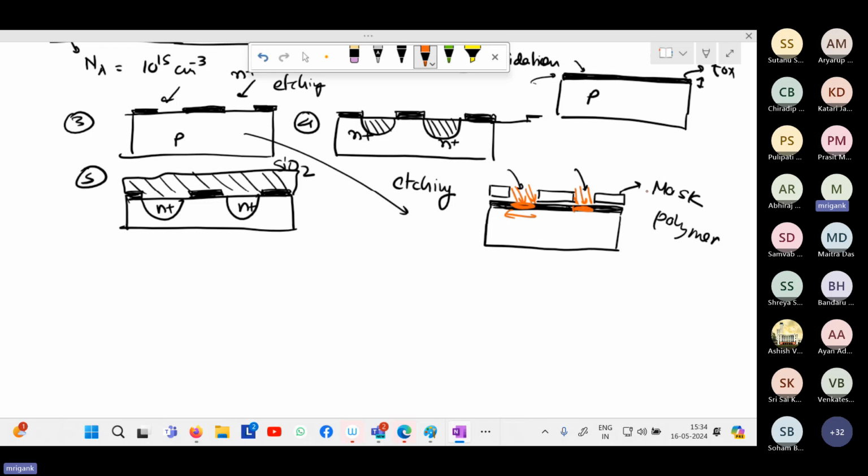In the entire MOSFET fabrication, you can see that I have still not shown all the steps. Every step will have multiple masks. And these are nanoscale masks, very small dimensions. They need to be positioned very accurately, nanometer precision, sub-nanometer precision. And then the processes like etching, doping, etc. need to be carried out. Once this is opened, you can apply the doping. The same mask can work on the doping also, because ultimately the opened area will only accept the doping.